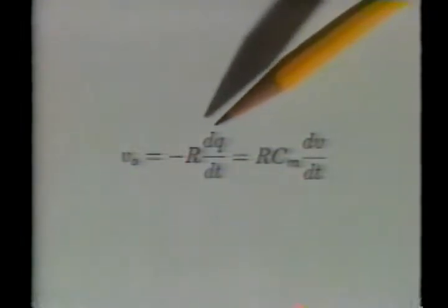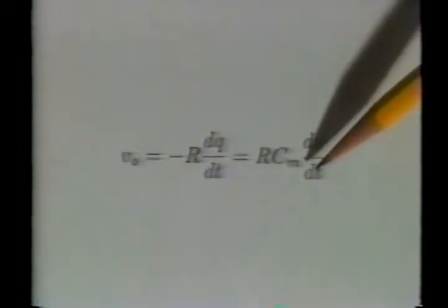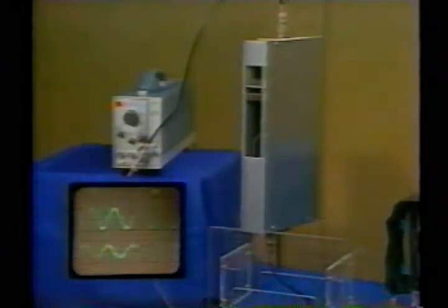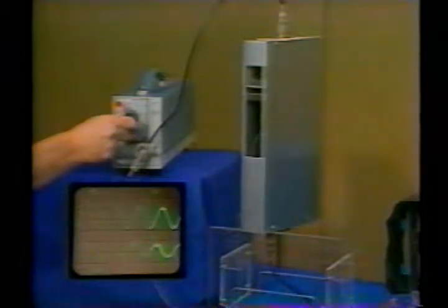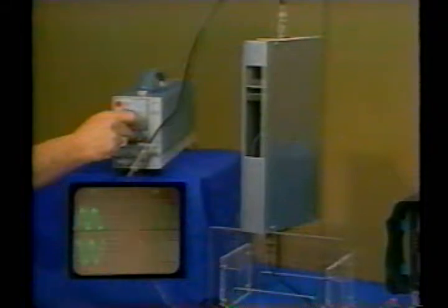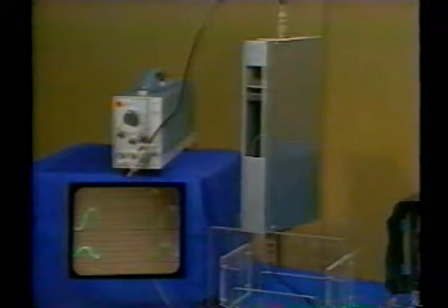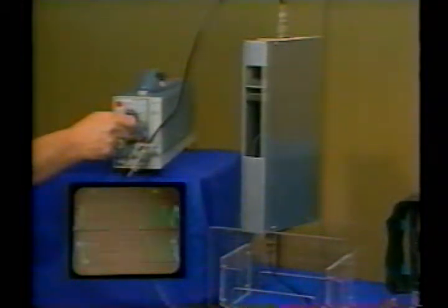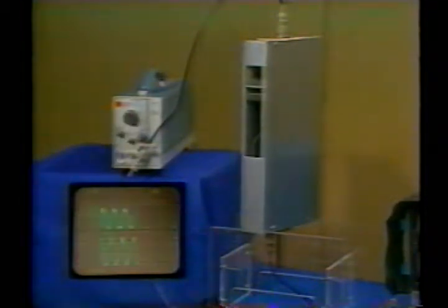However, if the frequency is taken from 1,000 hertz to 2,000 hertz, the output ceases to be linear in the frequency. With the frequency this high, the current through the output resistor is too large to make the potential of the output electrode negligible. We have demonstrated how solutions to Laplace's equation that are periodic in one direction decay in the perpendicular direction.